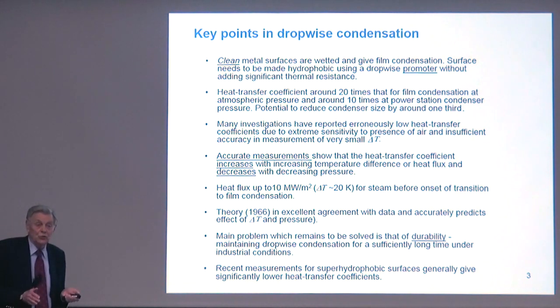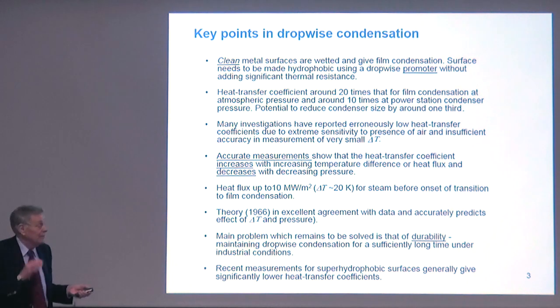Analogous to the transition of nucleate boiling to film boiling, at a high enough heat flux, you will have a transition from this. Even the non-wetted surface will form a complete film, but not until 10 megawatts per square meter. Theory, 1966, co-author me, is in excellent agreement with the accurate data.